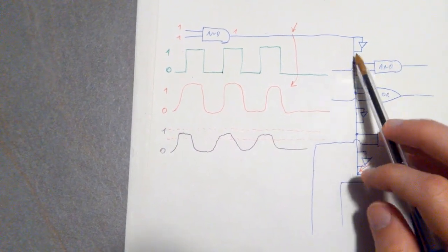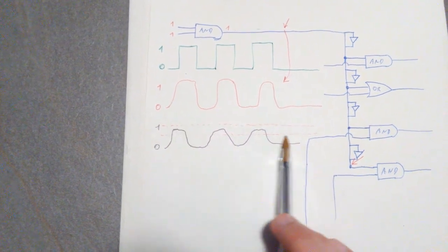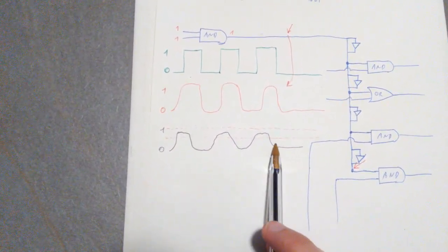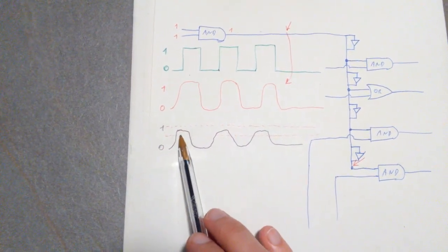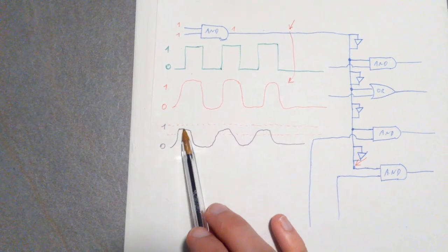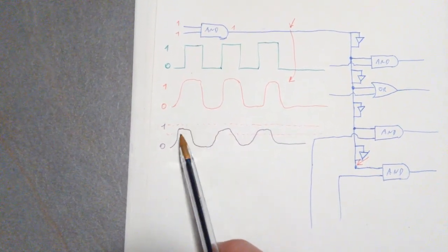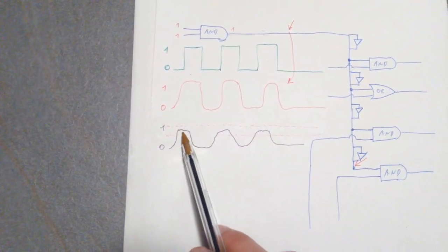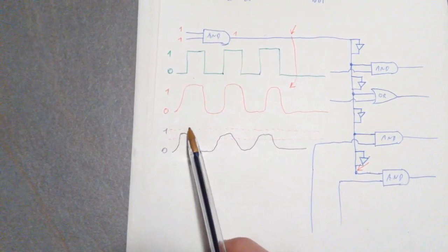So what do they do? Well, this buffer is getting this crappy wave, and saying, okay, it's actually above the threshold, so I know that it has to be 1. In Boolean algebra, it doesn't make sense to have a value between 0 and 1 as a voltage, so I know that it has to be expressed as 1.